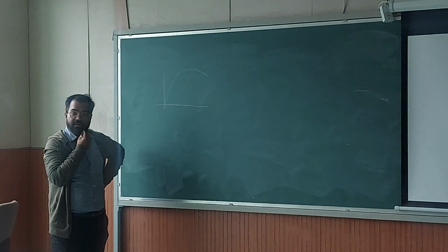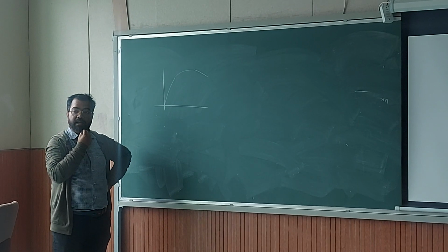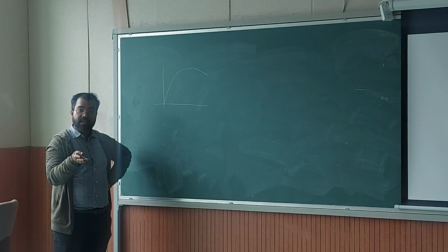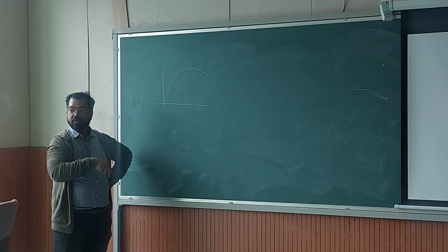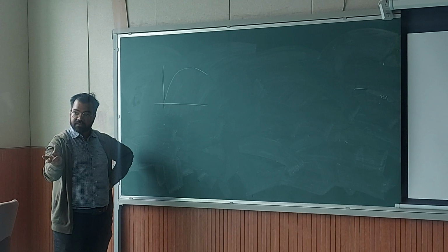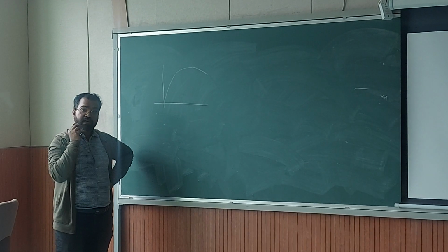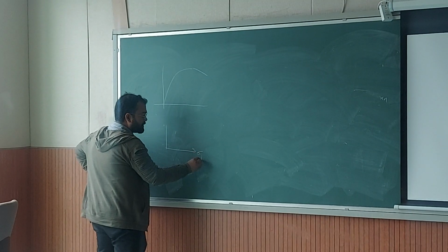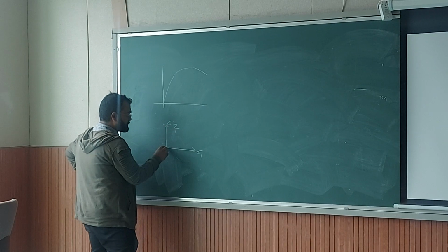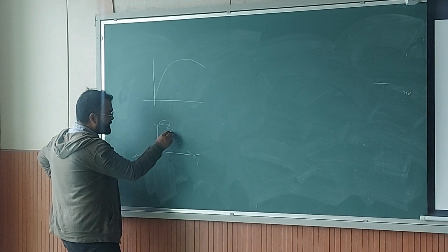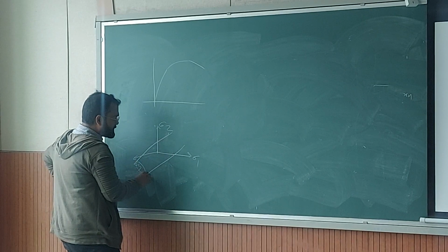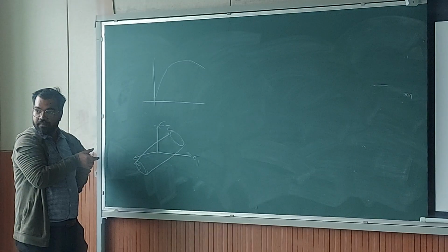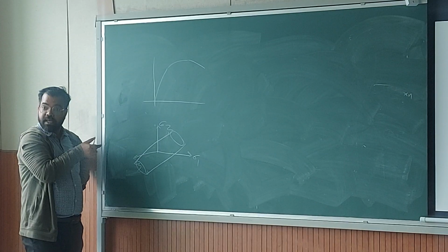So one way to define such damage was updating the yield function by accounting for the nucleation of void which is happening and the current status of void volume fraction, subtraction of that from the yield function, and keep on updating the yield function. So in that case, what will happen? On your sigma 1, sigma 2, sigma 3 diagram, the von Mises ellipse which you had, in this case, this ellipse will be decreasing in radius with damage increment.